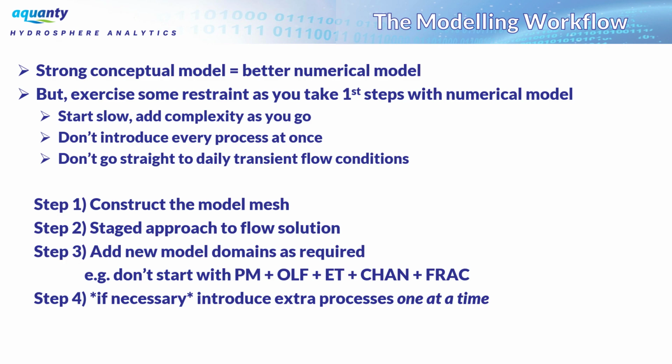So that's just, again, a couple of examples to illustrate poorly conceptualized boundary conditions. Boundary conditions, they are the way that water flows into and out of your model. So you need to think about them in realistic terms and really understand how those boundary conditions work numerically. We've got a full theory manual. You've got to read up on each of these boundary conditions and be confident that you're not creating a numerically weird situation where your boundary conditions are going to interact in an unrealistic way.